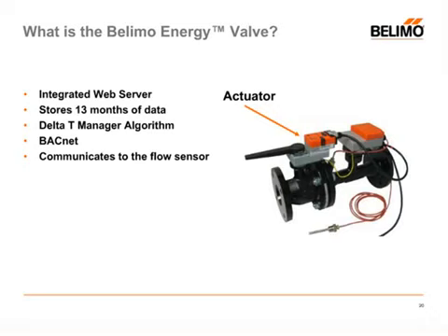This also is integrated with BACnet, has BACnet capability. In the upcoming slides, I'm going to talk about the BACnet information that we're able to communicate with. And this actuator is also what communicates to the flow sensor. So that's the basic actuator there. Very smart actuator, very strong actuator integrated into the valve body itself.